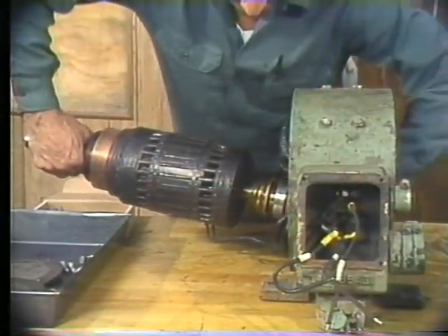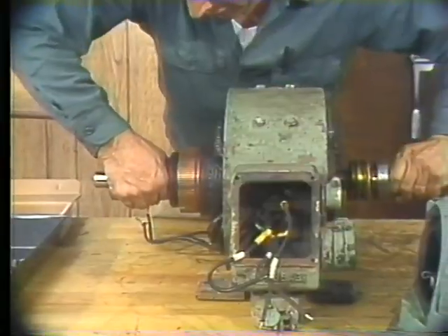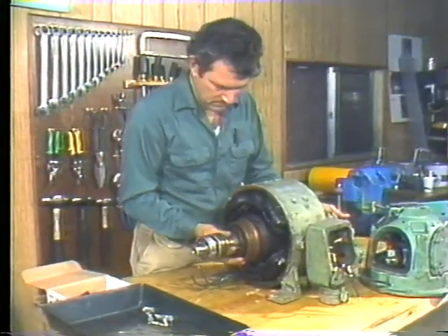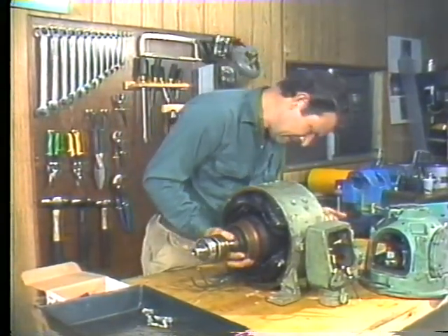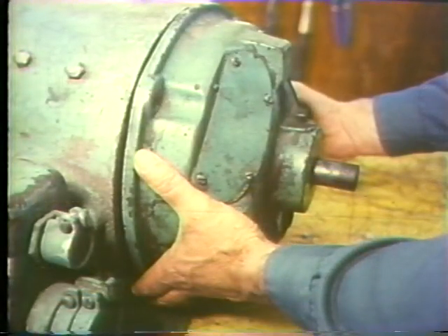First step is to carefully place the armature in the motor frame. Don't slide the armature on the pole pieces. Check your frame marks to be sure it's in right. End bells are next. Put on the one that's farthest from the commutator first.